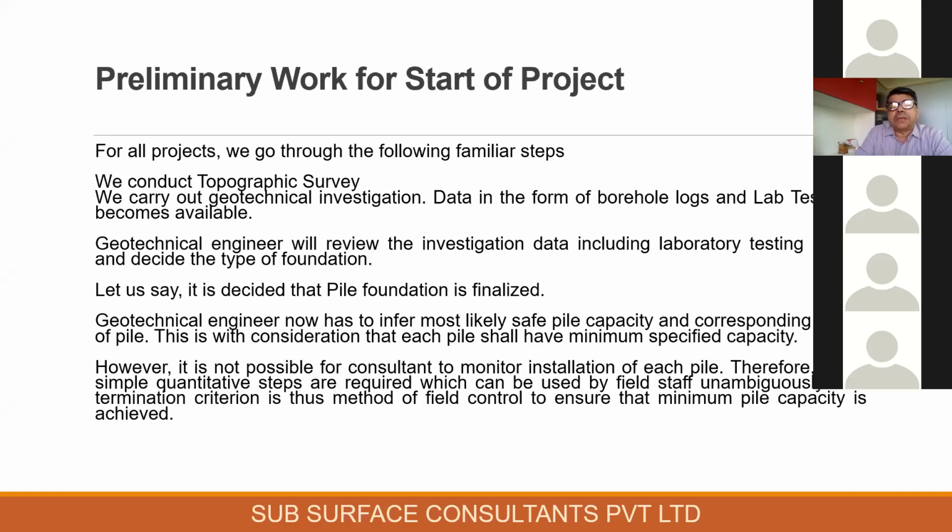Now, once this data is put together, it is collated and taken to a geotechnical engineer or a consultant. He will review this data and come up with the answer whether he requires a shallow foundation or a pile foundation. Shallow foundations are of course the preferred foundations, because casting of the foundation is done right in front of us and the quality of the concrete can be assured. However, there are times and reasons that we need to go for a pile foundation. So let us say that it is decided that pile foundation is finalized.